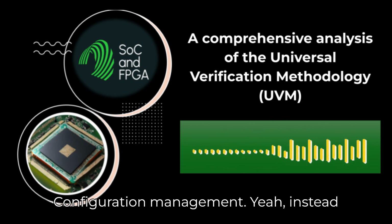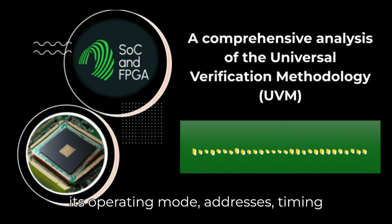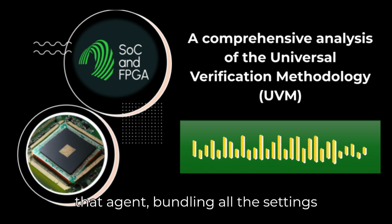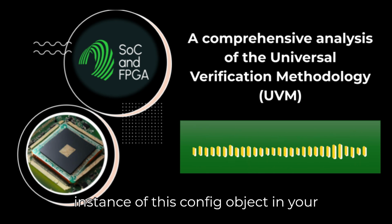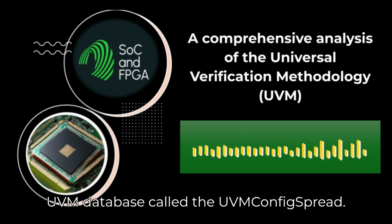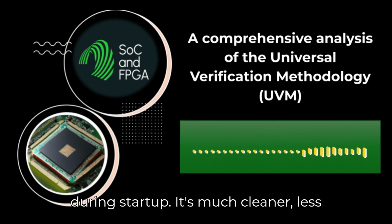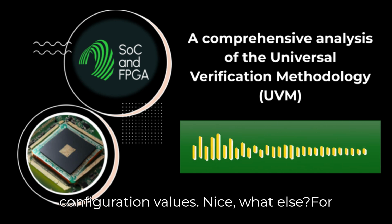Configuration management? Yeah. Instead of setting dozens of individual variables to configure, say, a complex agent, like its operating mode, addresses, timing parameters, you create a single dedicated configuration object class for that agent. Bundling all the settings together. Exactly. You create one instance of this config object in your test, set all its fields, and then you place this single object into a central UVM database called the UVM config DB. The agent then retrieves this configuration object from the database during startup. It's much cleaner, less error-prone, and often more performant than setting tons of individual configuration values.